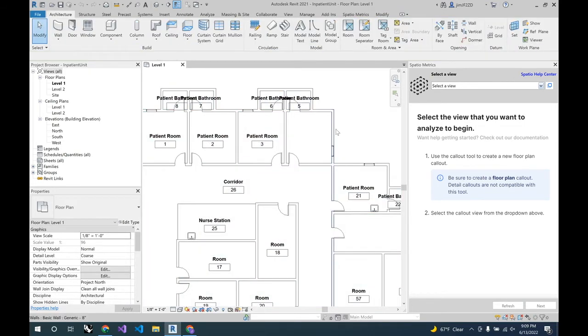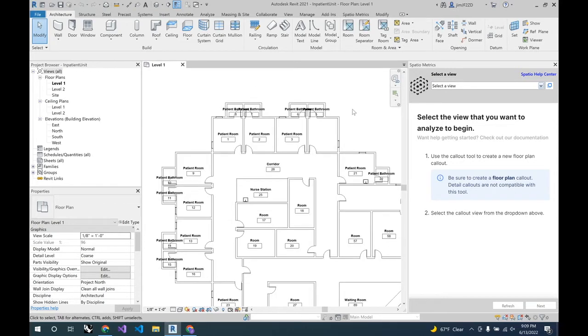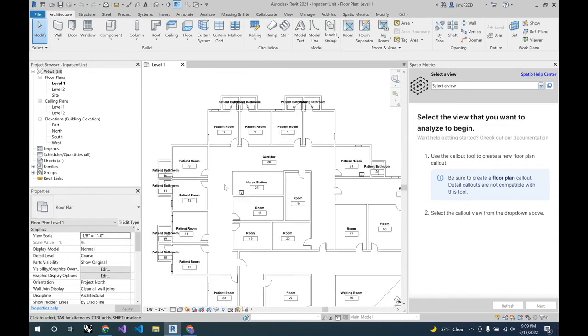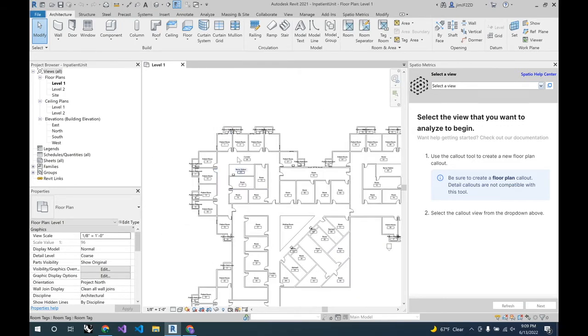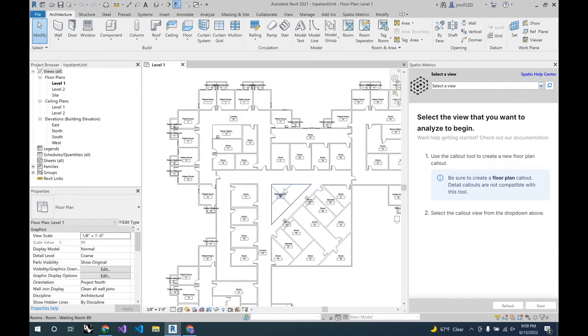Using Revit room elements works great because it really automates the process, but you can also use filled regions instead. The second set is walls, windows, and doors. If you include these in the model, the plugin will automatically generate visual barriers for you by extracting the center lines from walls and cutting out openings for windows and doors. These visual barriers will affect visibility analyses like window access, privacy, and views. Alternatively, you can create visual barriers from other inputs like detail lines, column bounding boxes, and room outlines.